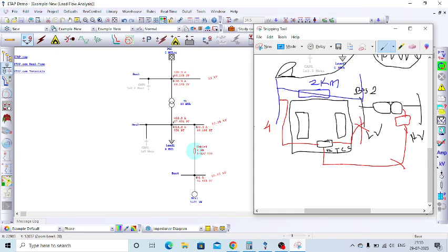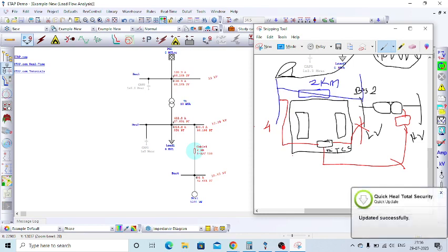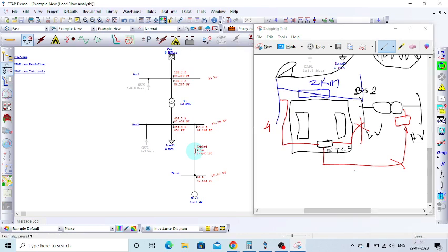Okay, taking the input near the bus is very easy, but a 2 kilometer auxiliary cable we need to lay. So we have to lay a 2 kilometer auxiliary cable, and there are some technical challenges in that. In order to avoid those challenges, in most cases we normally consider the immediate transformer LV bus voltage, which is taken and given to the RTCC that will control the transformer tap changer.